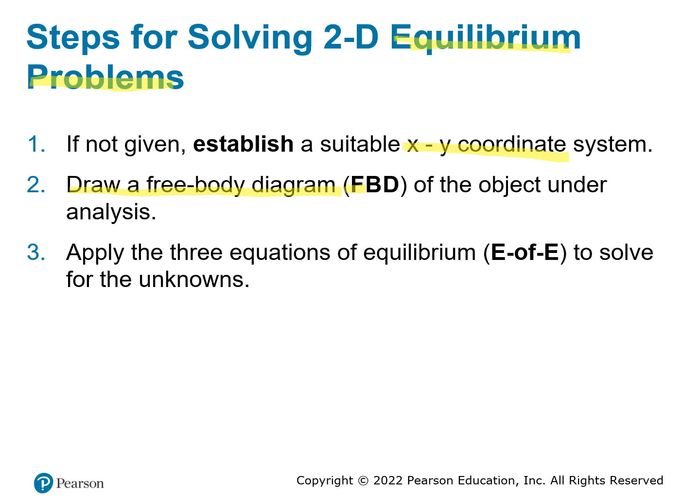When you do a free body diagram, you not only isolate the object, you also need to identify the forces acting on the object, including the things we mentioned in the previous video, supporting forces, supporting reactions. If you have a roller, it's going to be a normal force. If it's a pin, you have supporting forces X and Y. If that is a fixed end, you have both supporting force and a moment.